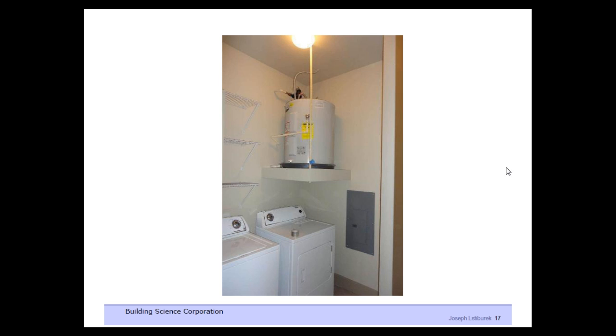And so the only technology available, well, there are two. One is practical and the other is yet to be figured out practically. One is a condensing dryer, but there isn't a vent to the outside. And the other is providing a dedicated interlocked makeup air fan into the room or the space where the exhaust dryer is functioning. Easy to say, not easy to do. Next.